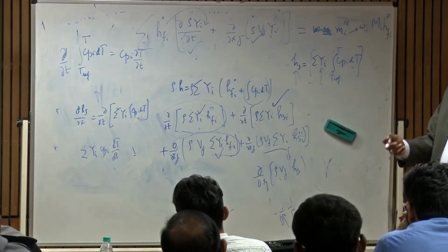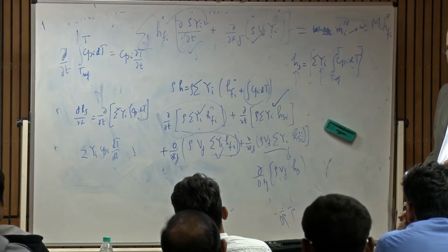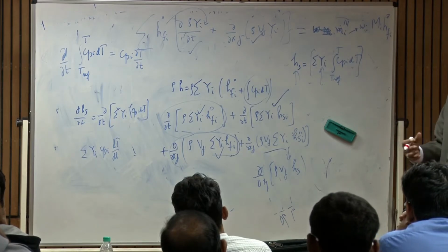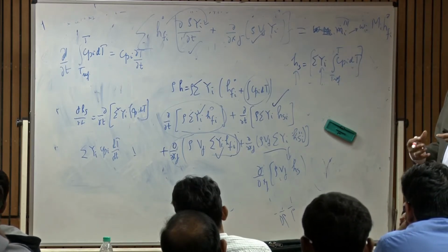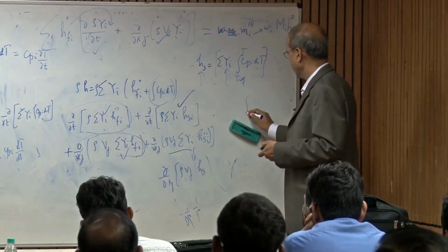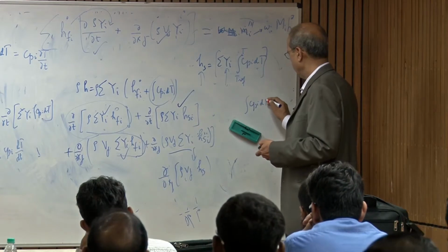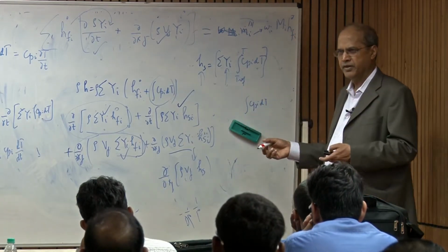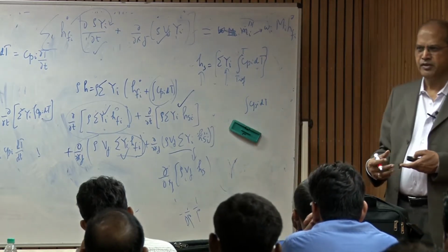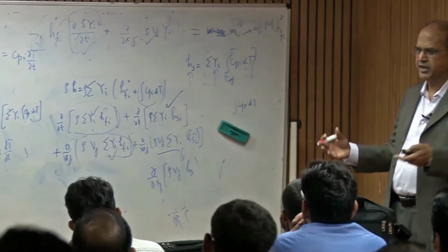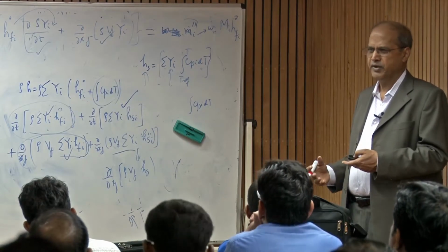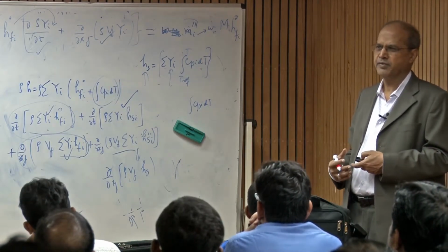Okay. So when you do equilibrium adiabatic flame temperature, you can go back and look at it. You do more or less the same thing. You calculate the enthalpy of reaction, and then you have terms like this for CO2, H2O, and then by iteration you calculate the temperature. So it's the same thing you are doing here when you have three-dimensional reacting flow. You compute Hs, and from Hs you get temperature.